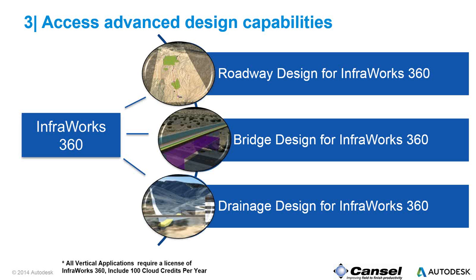You can design profiles with actual vertical curves. With the Infraworks that comes with the suite of products, you can design profiles, you can design roads with curves. But when they're exported, say, to Civil 3D, they are essentially spline objects. Not spline exactly, but they're spline-like.